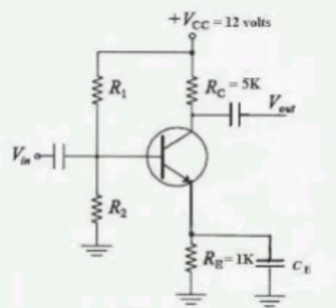Why is the induction machine called a generalized transformer? An induction machine is termed a generalized transformer due to the following reasons. Energy transfer mechanism. Just like a transformer transfers energy from its primary to its secondary winding via magnetic induction, an induction machine transfers energy from the stator, acting as a primary winding, to the rotor, acting as a secondary winding. The major difference is that in an induction machine, the secondary rotor winding is movable and creates mechanical energy related to motion. In a transformer, the windings are stationary and the transfer of energy is purely electrical.